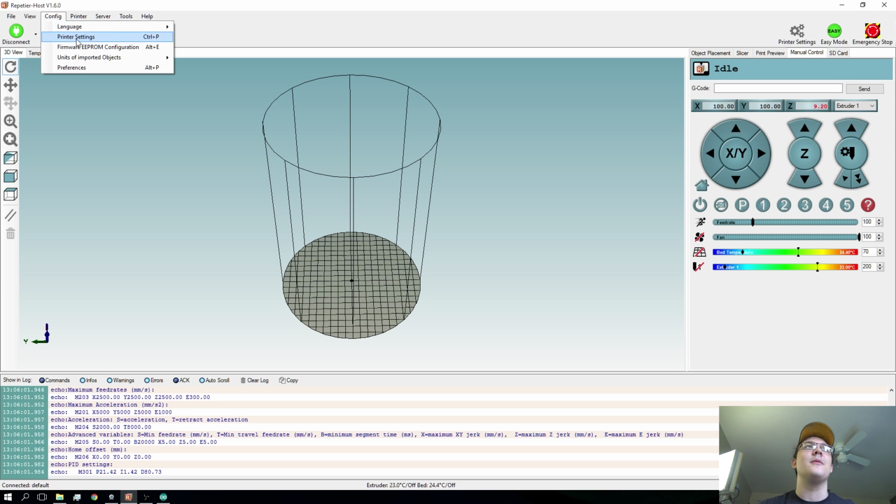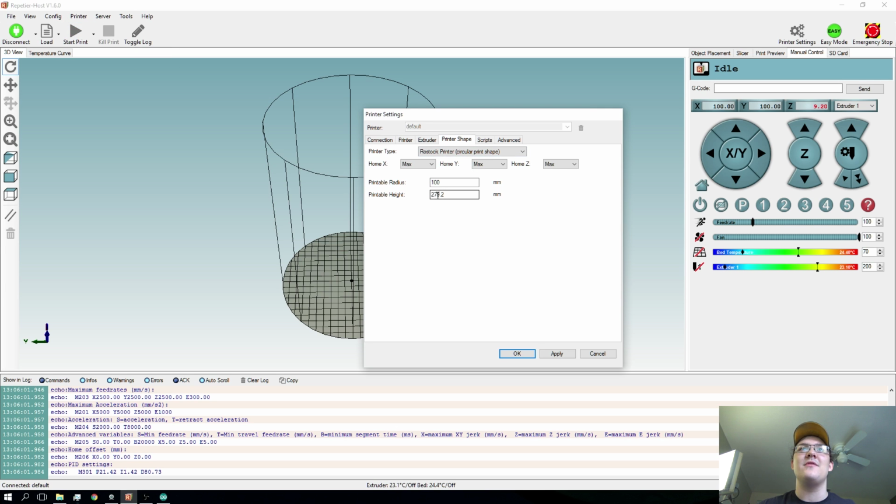So, for example, I have 279.2. If I subtract 9.2, then it's going to give me 270, which is fine. You can use 270. I have mine slightly offset, just ever so slightly, which is why I have it at 269.2. Having it slightly offset means I don't have to worry about the bed height. It's just a bed height thing. That's all it is. So I would probably recommend you slightly offset it by a little bit. This is 0.8 millimeter that I have it offset at.